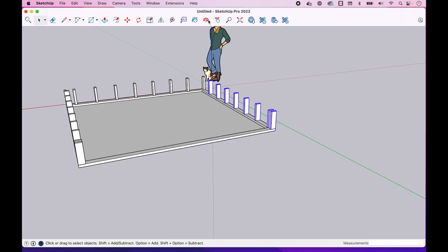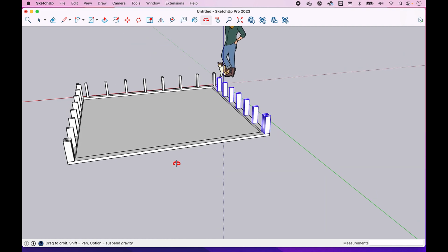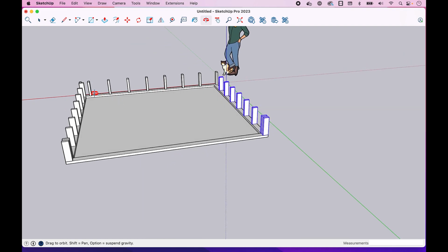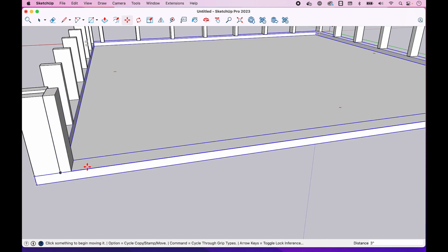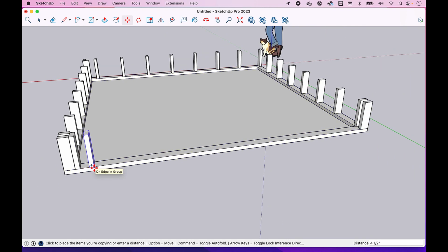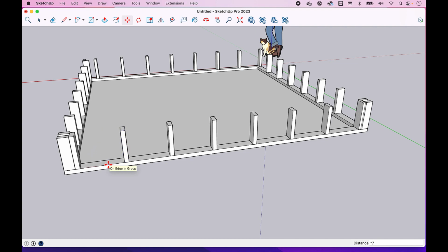And then likewise, we could do that with that back wall. Or as we said, another option is just to grab one of these, hit the Option key, come in, let's pull that tight, hit the Option key, we're going to move 16. And then we'll go times 7 to see how that looks. Maybe times 6 is good enough.